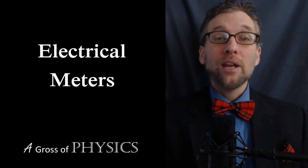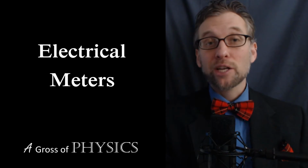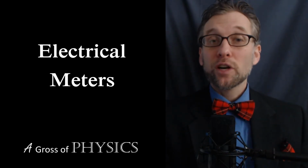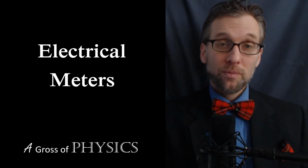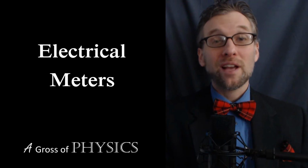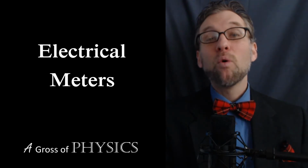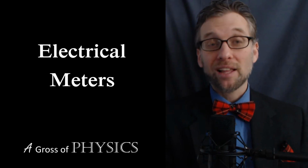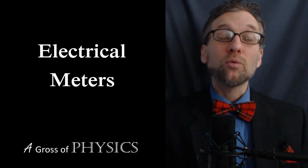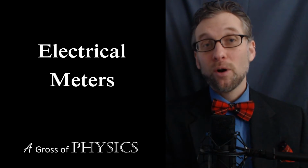And when we do that, we're going to want to be able to check our results theoretically to the actual values. When we've been solving circuit problems in our classroom and our lecture, we always assume that the wires have zero resistance. Of course, wires do have resistance, and the more we have in terms of the length of the wire, the more resistance there will be. So using a meter will allow us to see how close to the actual theoretical values our components have.